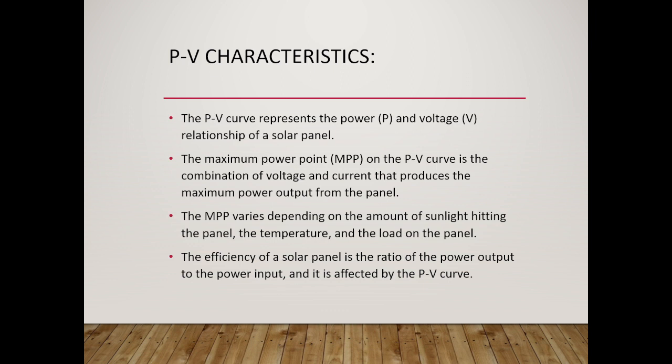The MPP varies depending upon the amount of sunlight hitting the panel, the temperature and the load on the panel. The efficiency of a solar panel is the ratio of the power output to the power input, and it is affected by the PV curve.